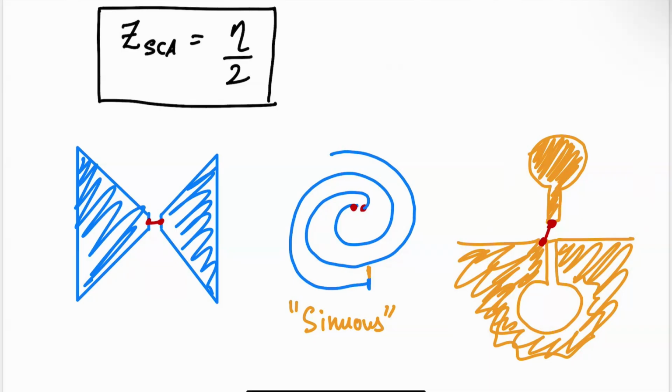Whereas the spiral is quite a symmetric structure. So over different parts of the band, different regions of the spiral radiate. So maybe this diameter, this part radiates at the higher frequencies, whereas at the lower frequencies, the outer arms radiate. But they are all kind of circular in shape, right? So you can get very consistent radiation pattern over the entire band.